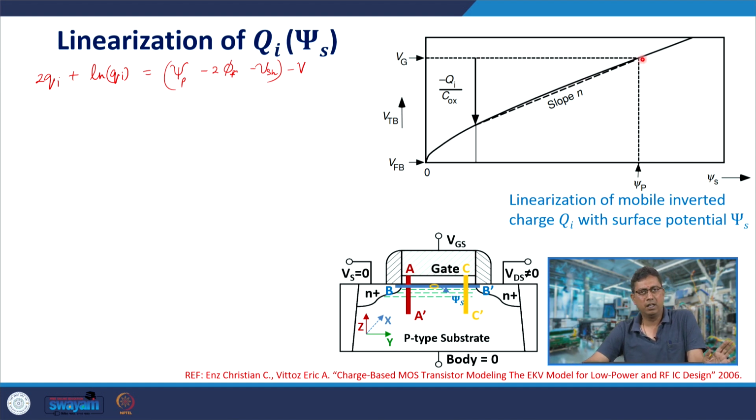That is because of our linearized model, as we had discussed in the previous lecture. It is never really 0, but in our model it becomes 0 and that we call the pinch off potential, where we can consider the inversion charge to be 0. That is, for a given gate voltage, it is a unique value.